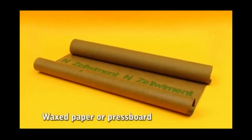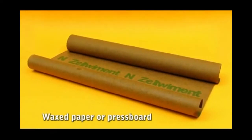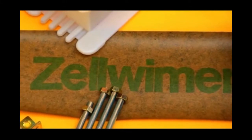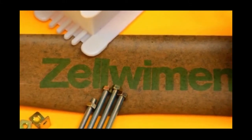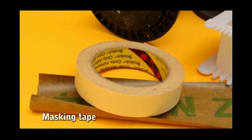Wax paper or press board. This roll is used to isolate the windings or coils of wire from each other. It has a paraffin layer which makes it flexible and ductile. It also seals out moisture and gives heat resistance, preventing crystallizing. Masking tape. It is used to hold paper and wire between the windings.